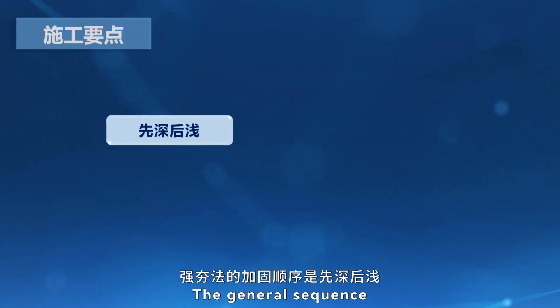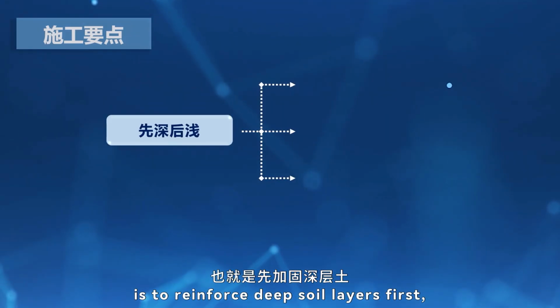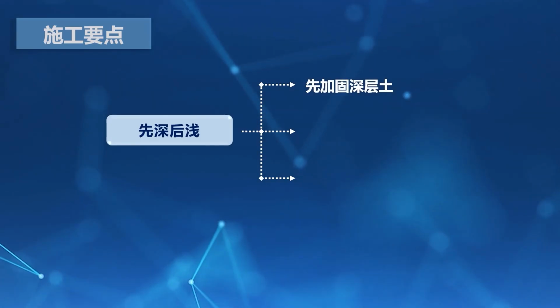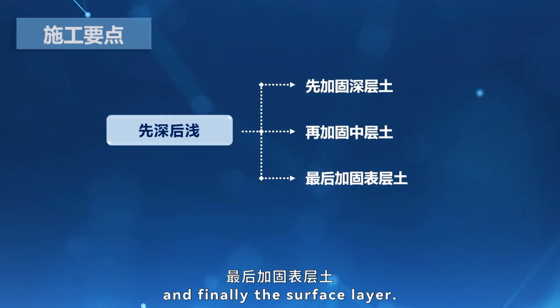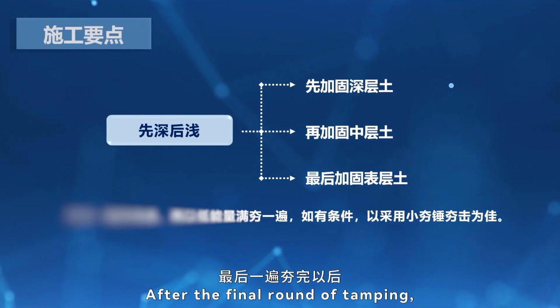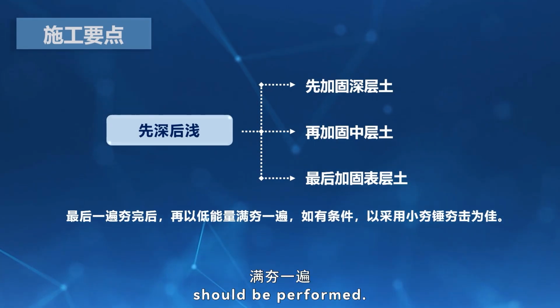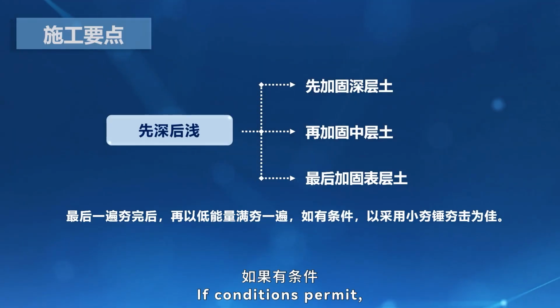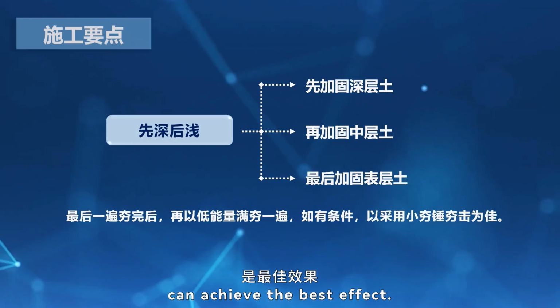The general sequence is to reinforce deep soil layers first, then middle layers, and finally the surface layer. After the final round of tamping, a full coverage tamping with low energy should be performed. If conditions permit, using a smaller tamper for surface compaction can achieve the best effect.